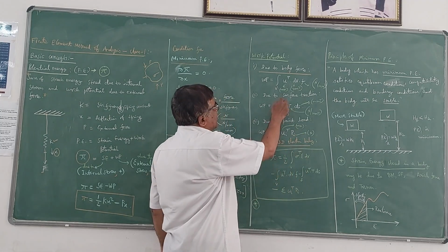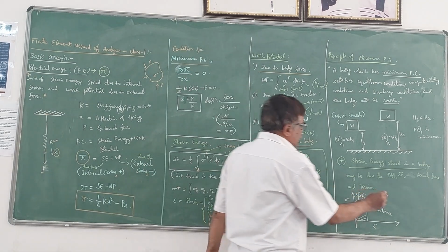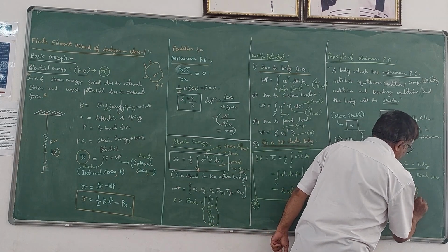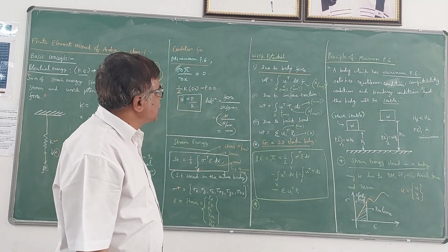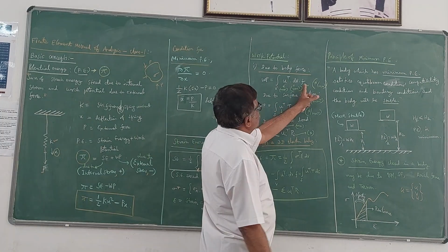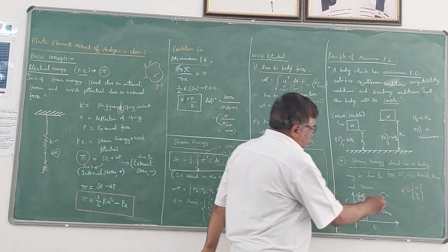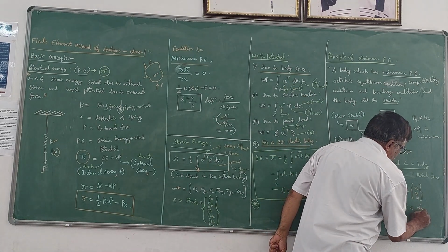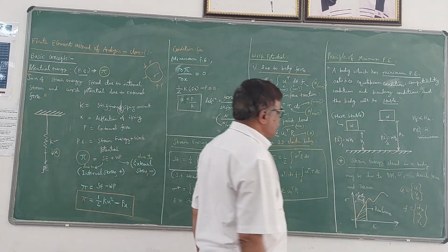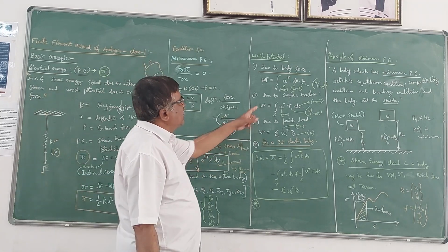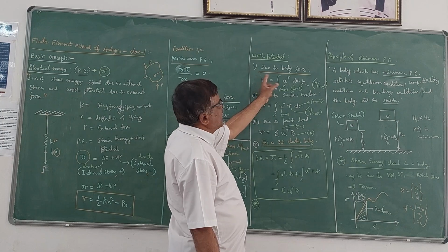Here U is nothing but the displacement. Please note that U is nothing but u, v, w, the displacements along x, y, z directions respectively. F is the force vector and dV is the volume expression. F can be written as Fx, Fy, Fz, the forces acting along all 3 directions, x, y, z, for a 3-dimensional element. When you take the product and integrate with respect to volume, you are going to get the work potential due to body force.